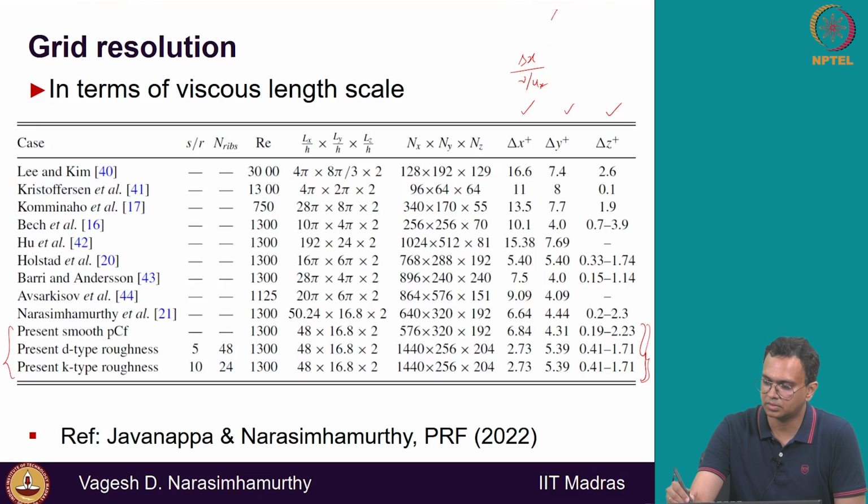Our delta x is now the same order of magnitude as the viscous length scale. It should not be 10 times larger. This is in the x direction, and delta y is actually the spanwise, and this is the wall normal. So it's the other way. Let's call this y in our terminology, and this is z. Okay, so wall normal is, you see, much tinier,